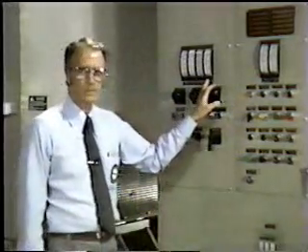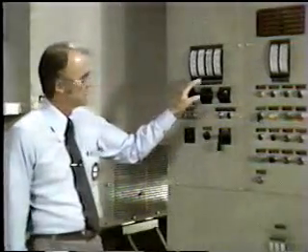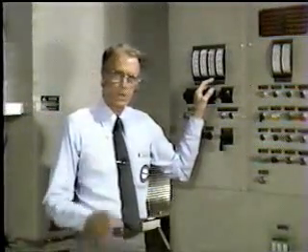The AC system incorporates four types of transformers to supply voltage for operation. The current transformer is very accurate and consistent in its output. The current transformer steps up or steps down amperage for use by the instrumentation. The watt var meter, the ammeter, and the frequency meter use the current transformer's accurate output to measure generator performance.